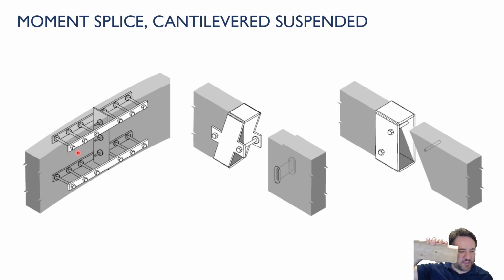So if my moisture content goes down, then my wood is going to want to shrink in between those two bolts, which means that it is going to make a tension perpendicular stress across between those two bolts, which is going to want to crack that piece of wood apart. So it's better to separate those.